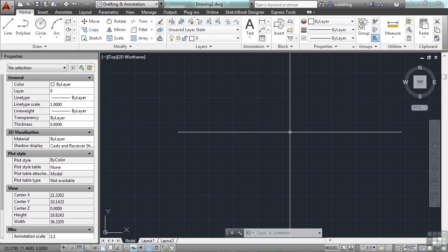The best part is that you don't even have to open up all the drawings, or any of them at all, really. There's a publish manager that you can use, and you can open it up while in any file and have it print any tab from any drawing, regardless if you've opened it up or not. This is why we use CAD.